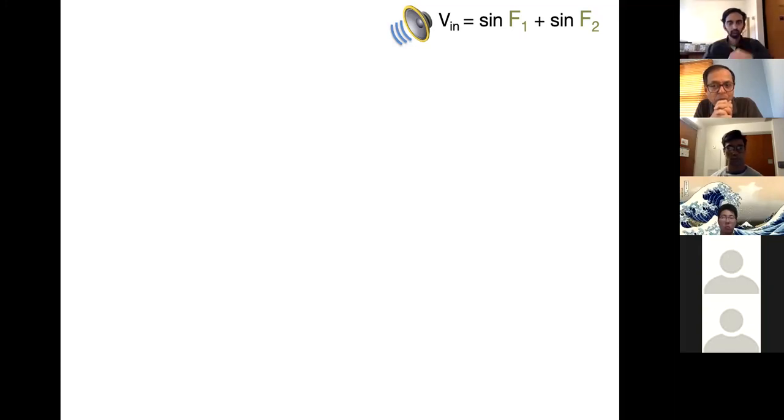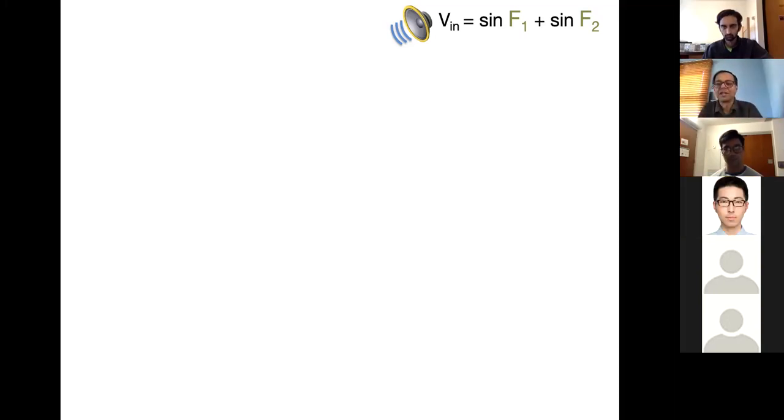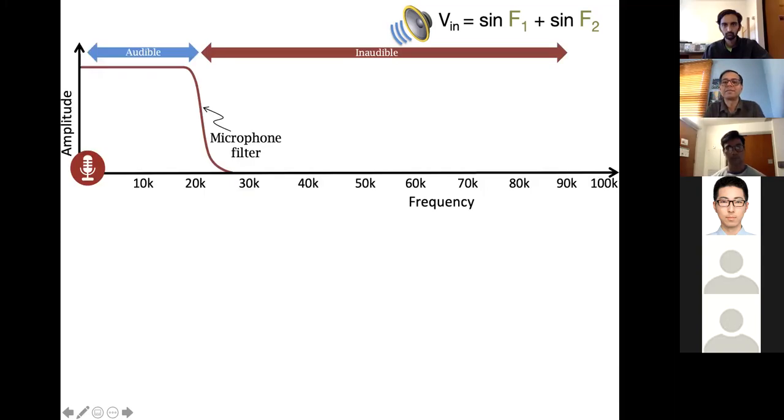Spikes corresponding to F1 and F2. Well, there are two spikes for sine, one point down, one point up, so 4 spikes total: F1, F2, minus F1, minus F2. Agree? And minus F1, minus F2 is nothing but the max frequency minus F1, the max frequency minus F2, because we remember that it's symmetric. Right? Very good. So sine F1 plus sine F2 gives me 2 spikes.